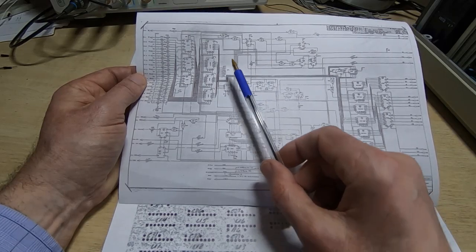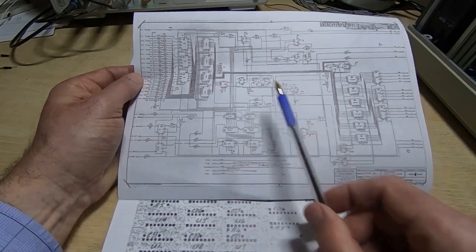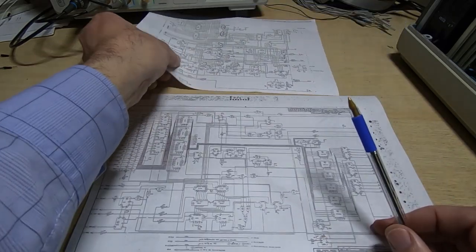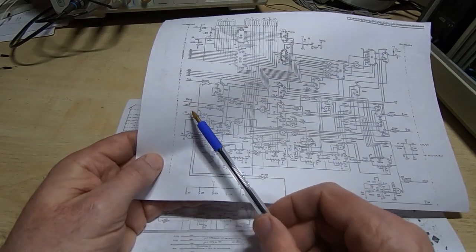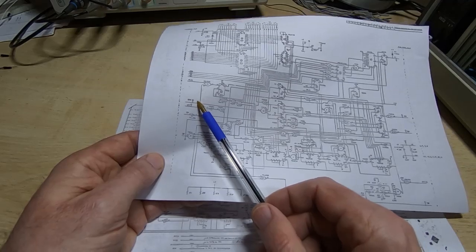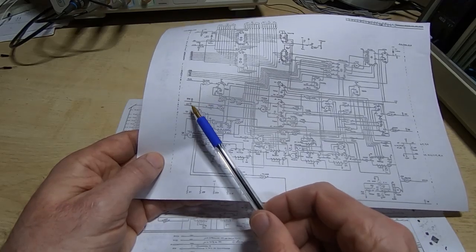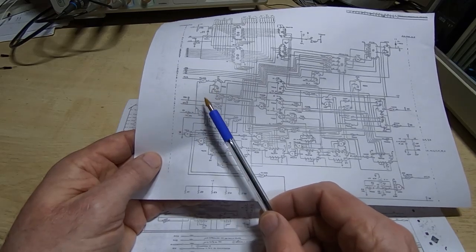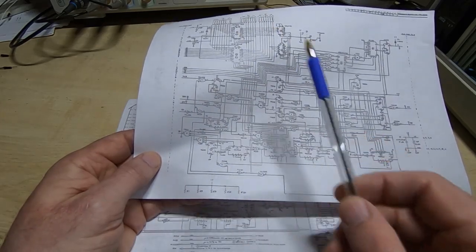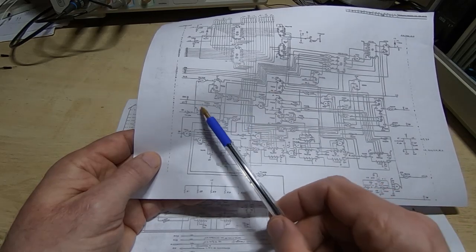So to try and explain exactly what's going on here, we'll start at this end. I'll attach a scope to the 3 control lines for this. So that's the NW, new word, new line, and new page outputs. There are test points on this card. So I'll attach the scope to that, and we'll just check this is running.